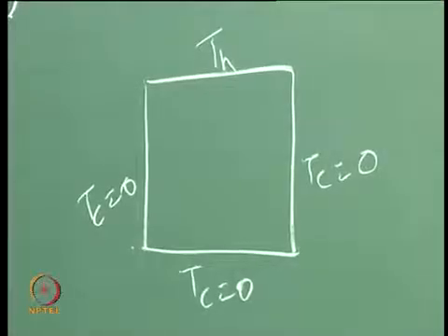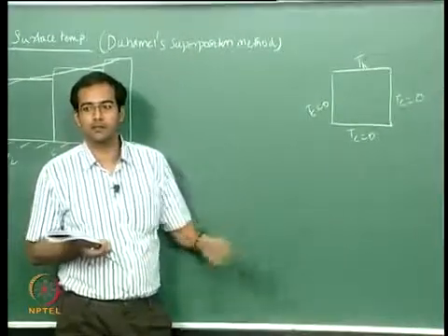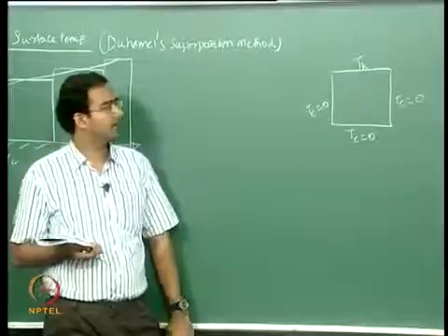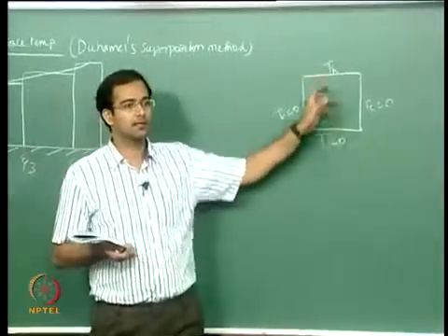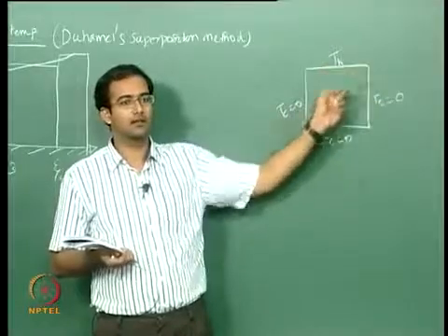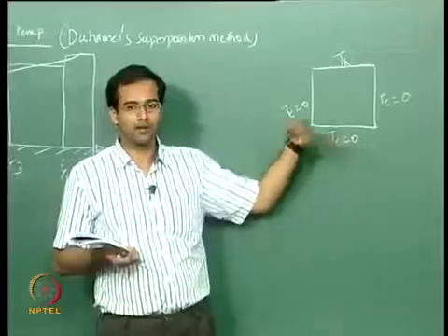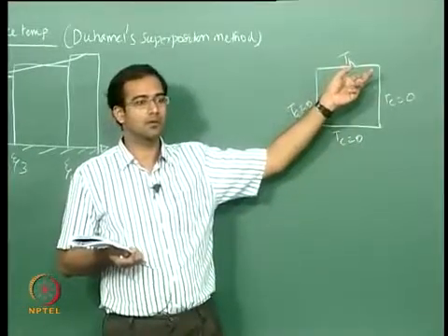For this you can solve the 2D conduction equation by separation of variables. There will be an eigenvalue problem in this direction, where you have 2 homogeneous boundary conditions. In the other direction you apply the remaining homogeneous boundary condition, and finally the non-homogeneous boundary condition to get the final constants.